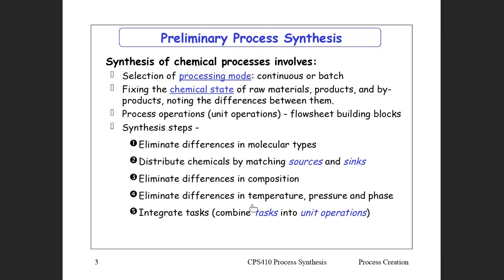When you compress with isentropic compression, the temperature always goes up. And so if you start with a vapor at its dew point, the temperature goes up more than the boiling point goes up, because you're increasing the pressure.